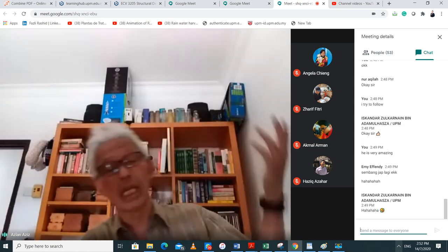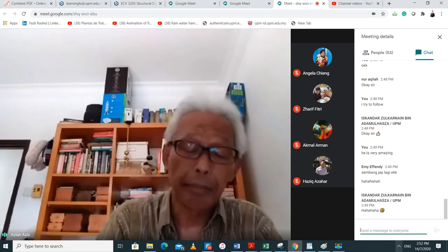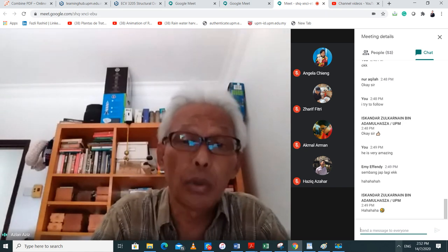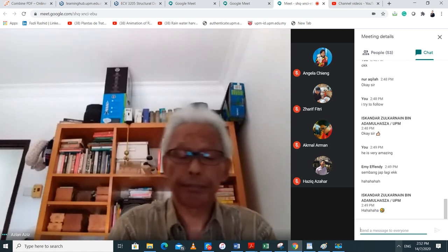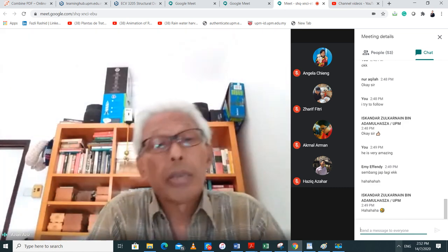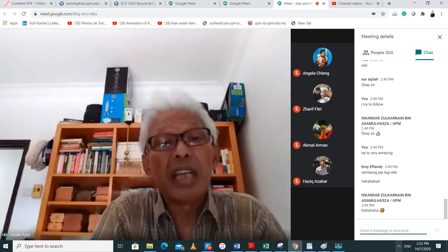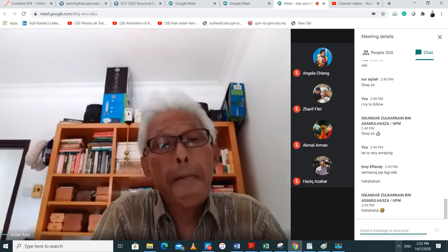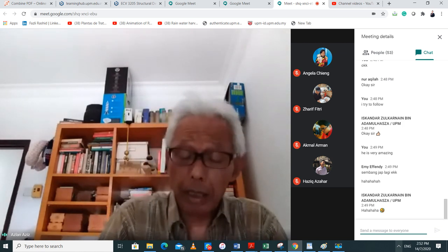So the allowable load, now the ultimate load, right, divided by the factor of safety for the load, which is 2.5, so you get 1168 kilonewton. Are we okay thus far? Yes? You know, ask me anything you like now. No? All right. I assume you get it.